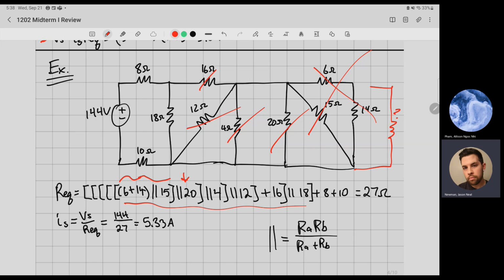So now this whole entire resistance, if you imagine all of this is gone over here, that whole amount is right here, but it's in series with 8 and 10. So you just take that whole amount and say plus 8 plus 10. And that's it. It's very useful. I know it's kind of daunting at first, but I recommend you all practice it, because once you get to ENA, this is very, very quick handiwork, and it's actually an acceptable method. And actually, it's even taught in ENA, I'm pretty sure. Anyways, so we're gonna move on.